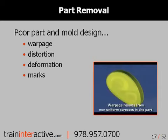It may cost a little more for the mold, but the part would run a faster cycle time. Also, since the force is evenly applied around the perimeter of the part, it won't distort, and the likelihood of the part becoming marked is reduced. In some cases, we've seen the use of air ejection by using poppet valves or porous steel to assist the ejection of thin-walled parts. When you use this type of system, the part will be ejected faster since the warm part is still soft and it blows off the core more easily.